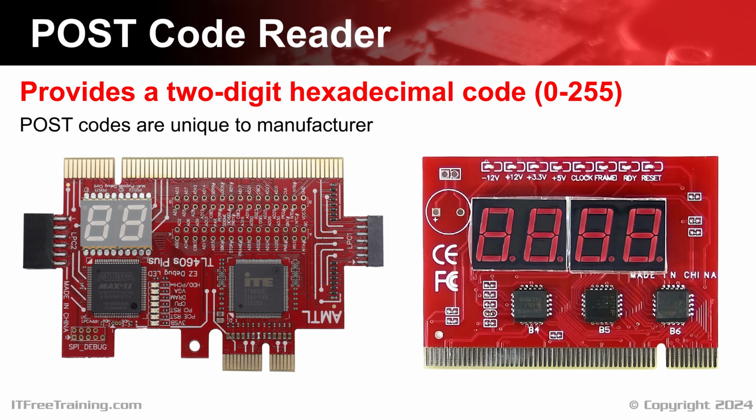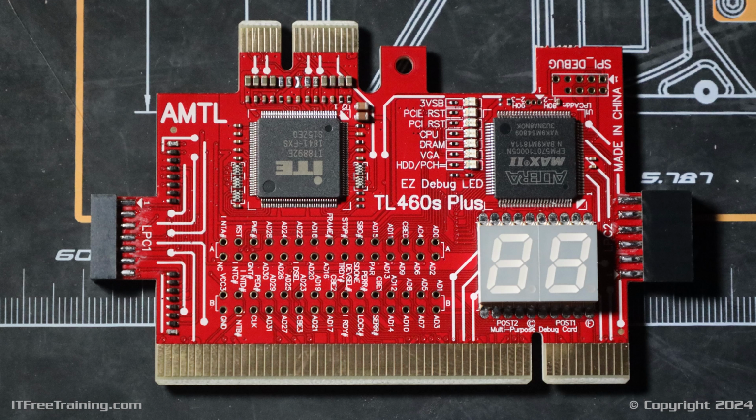To get a better understanding of how these codes work, I will use one to diagnose a problem on this computer. The computer has a faulty memory channel, thus any memory I put in two of the slots on the motherboard won't work. This PC postcard has 4 different connectors. You can see them on different ends of the card. If that is not enough, you will notice that there are holes in the card where you can plug in extra connectors if you have them and run leads to where you need them.